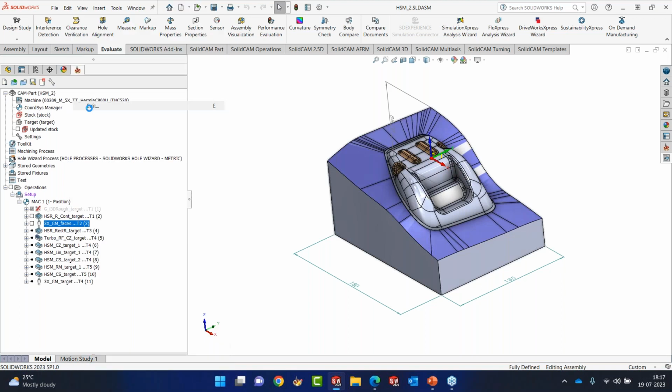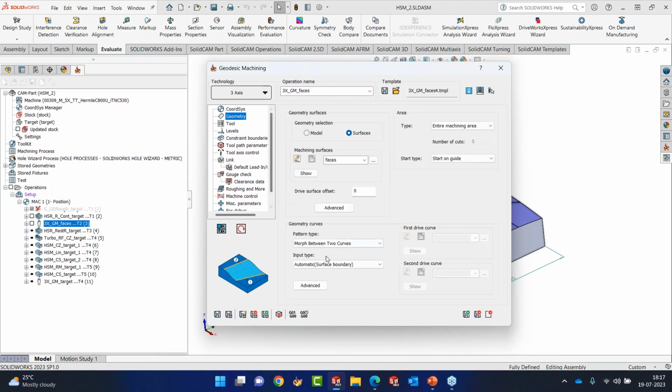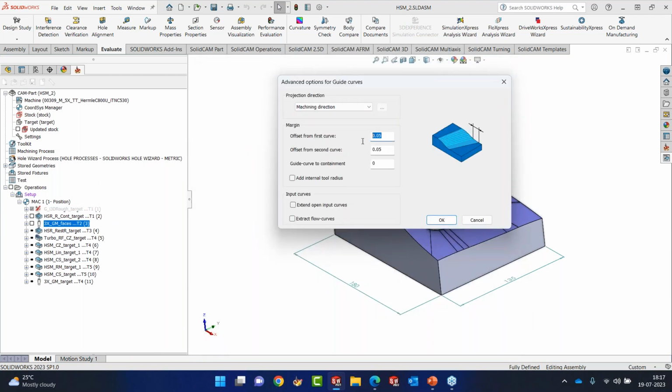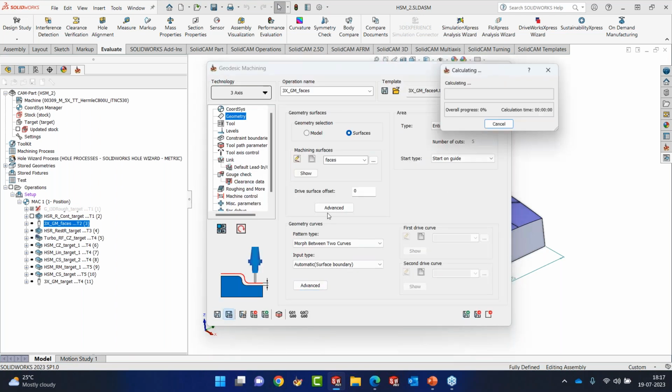So in such cases, because we have got a mechanism to catch the errors, I simply will go into the curve, and since it's starting, I'm going to say 6.5. That means half of the tool plus a value of 0.5, that is slightly more than half of the tool, is where it needs to start from, and not exactly from the exact edge.